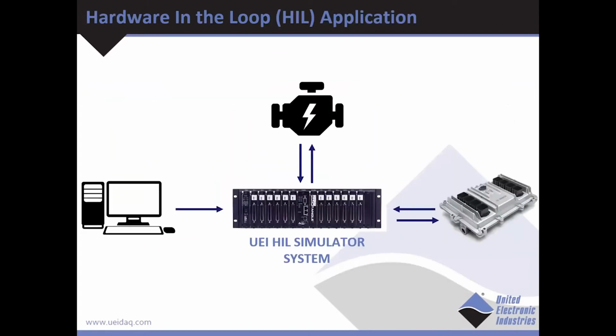So this shows a basic block diagram of a hardware in the loop testing setup. A HIL system basically includes an electrical emulation of sensors and actuators and a plant simulation model that runs on the host PC. These emulations act as the interface between the plant model and the embedded system under test, which would be an ECU, it can be an engine control unit, transmission control unit, or an ABS unit, whichever unit is under test. The value of each of these electrically emulated sensors is controlled by the plant simulation model, and it is read by the ECU.